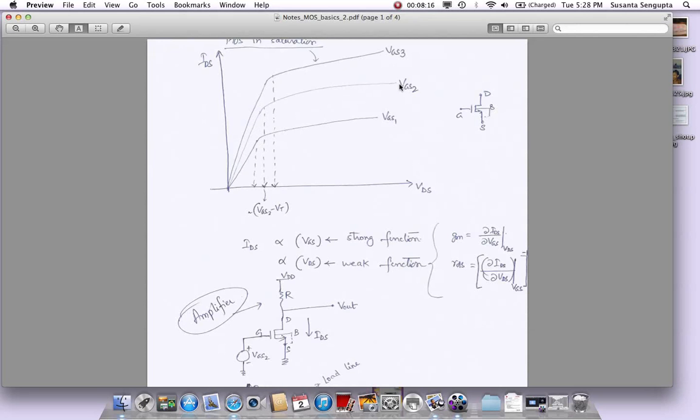So you will see that going forward, there is going to be a lot of stress on small signal, because we assume that this device, let's say if you are only talking about gate to source, was biased by a DC voltage, say 1 volt VGS. When we use this as an amplifier, we will only cause small perturbations compared to the DC value, and we will use these parameters, which are called small signal parameters.